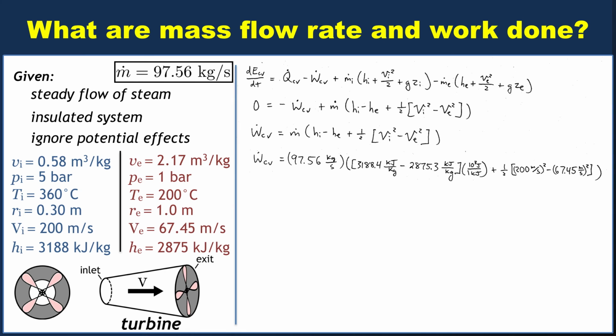All right, a lot of numbers in this calculation. One place where people slip up a lot is that extra factor of 1,000 being multiplied by the difference in specific enthalpies. The reason for that, remember, is that they were quoted in the back of the book in kilojoules per kilogram. If you want to match your units right, you better convert those to joules so that when you include that with the v squared terms, everything is in normal SI units. You don't want a factor of 1,000 floating around. Okay, so we'll reduce this a little bit. I'll keep m dot the same and just simplify the things in the second half parentheses.